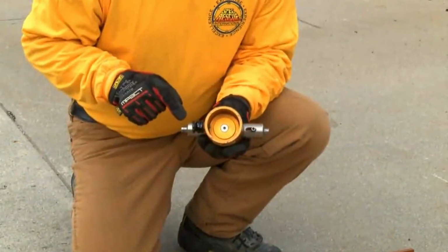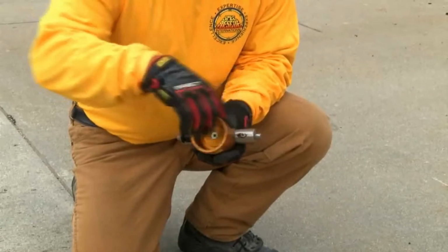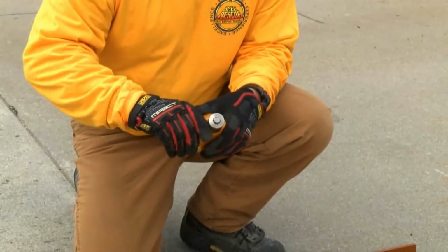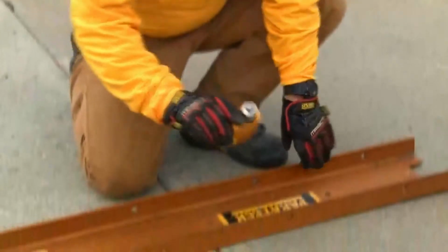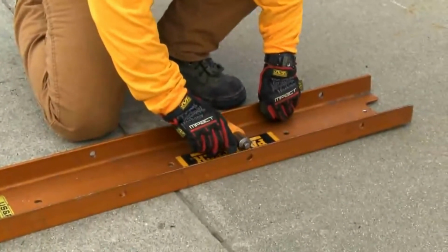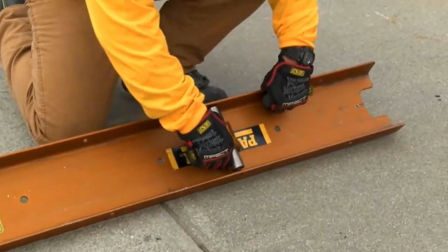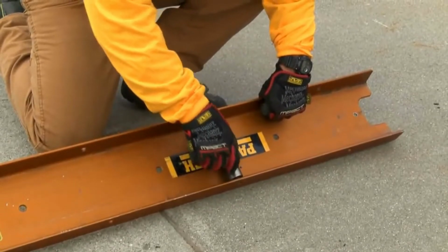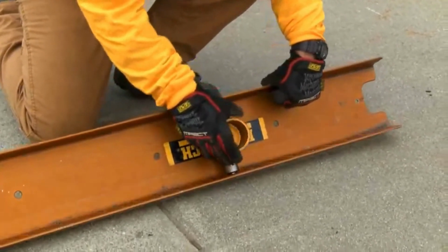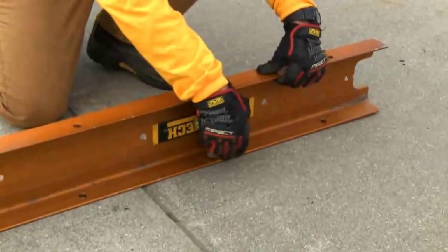Here we see one end of the latch base is solid and one end is movable and spring-loaded. The solid end goes in first, and then the spring-loaded end. Once the latch base is locked in place, turn the raker rail on its side. Attach the strut to the wall plate via the latch base.